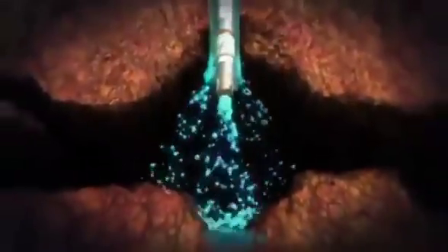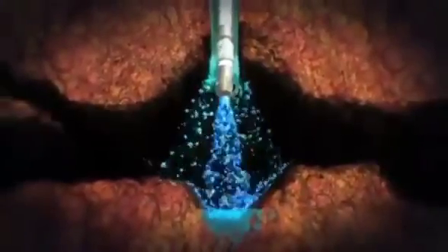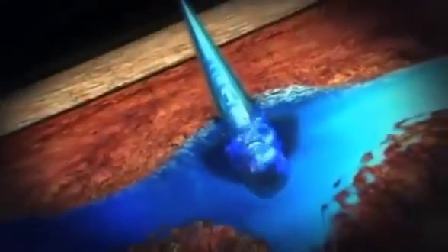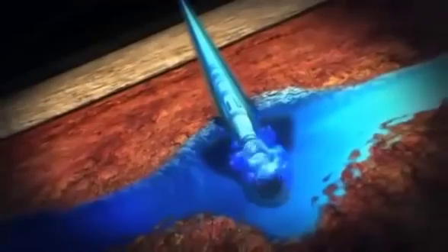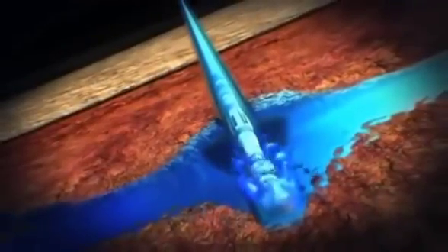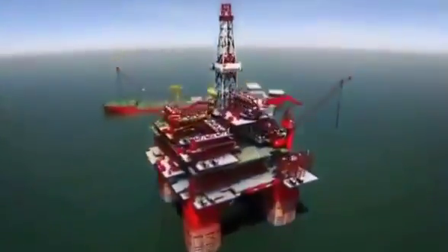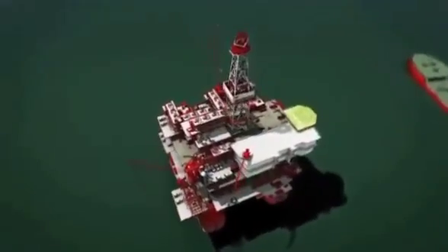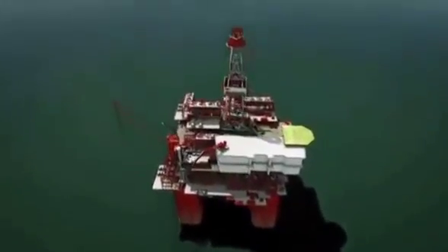A sacrificial brine or water is pumped through the drill string at normal rates to clean around the bottom hole assembly. Blocked by the fluid cap above it, this sacrificial fluid, along with produced formation fluids and cuttings, is injected into fractures or vugs in the formation. Because all the drilling fluid is injected, a large water supply is generally required for pressurized mudcap drilling.